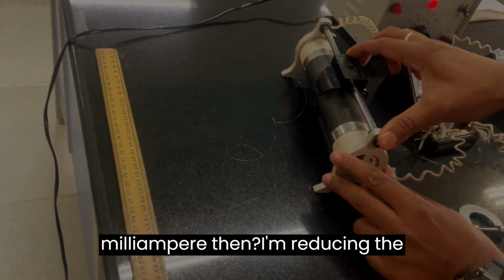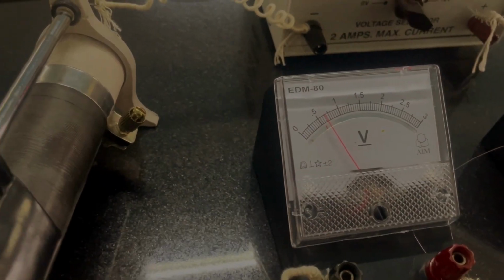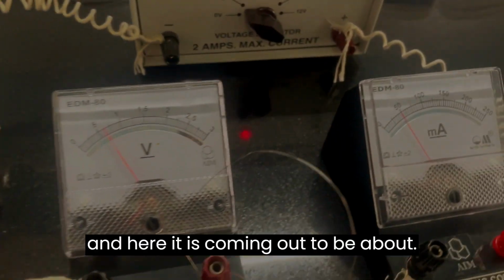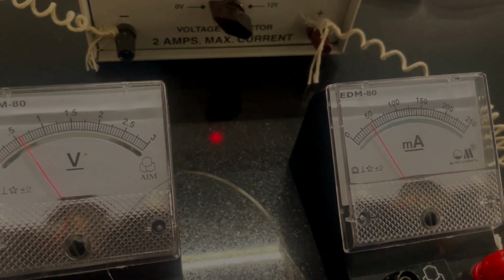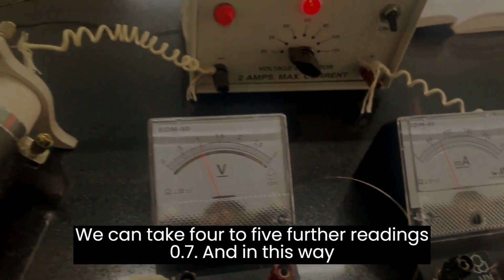Then I'm reducing the resistance. Now it is about 0.6, and here it is coming out to be about 0.7. We can take, and in this way 4 to 5 we shall be taking readings and draw a V versus I graph and get the value of R.